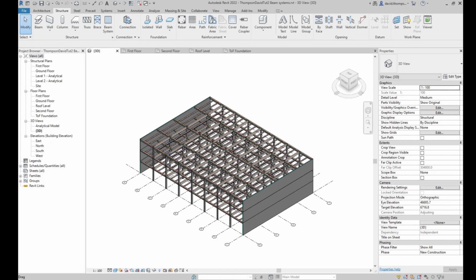First of all, we're going to look at the type of foundation. We'll go to Structure, and there are a few different options. Over here there's a whole section for foundation: isolated foundation, wall foundation, and slab foundation. Isolated foundations are placed under columns, and we've got plenty of columns, so we'll be using those. The wall is basically a strip foundation, which is what we're going to use for our shear walls. And a slab is a slab foundation, so think of a ground bearing slab or a raft foundation. That's what these are for.